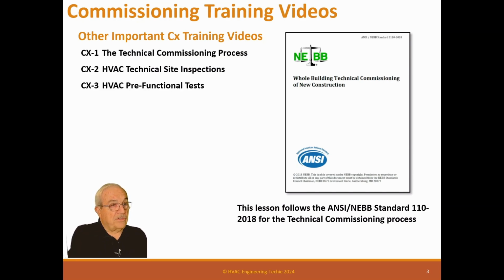Cx-3 is pre-functional tests, which tells you how to develop those tests and how to perform those tests. Cx-4 is point-to-point tests for control systems, really important to do. And this explains how to do them and what the process is to do that.